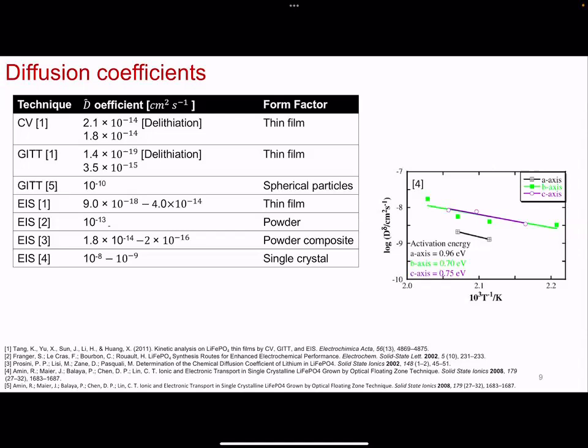So a lot of the studies that show really promising, let's say, fast C rate or high capacity, when you then go from coin cell to increasing mass loading and area loading to the form factors that you mentioned, it doesn't always translate. And you see that when you look at when studies come out of a material and then commercialization efforts, there's a huge lag in between, because of all the due diligence that people are trying and the engineering that goes into fabricating something.